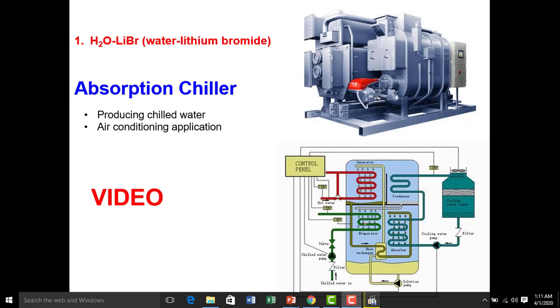Whereas if the pressure is low, let's say under vacuum, then the phase change of the water can be attained at 4.5 degrees C, at a vacuum pressure of 0.84 kilopascal. That means once the water from the condenser enters the evaporator, its temperature is about 4 degrees C. So the 4 degrees C water as a refrigerant